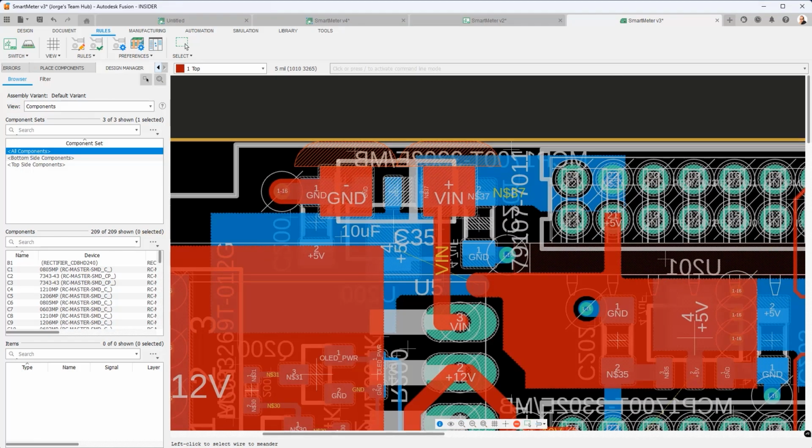So this in-component scope is very powerful because in this case we use the SMD pads of the component. But in-component contains everything that is in the component. So you can use the silkscreen lines. You can do clearances between components even. So keep in mind that scope. It is extremely powerful.